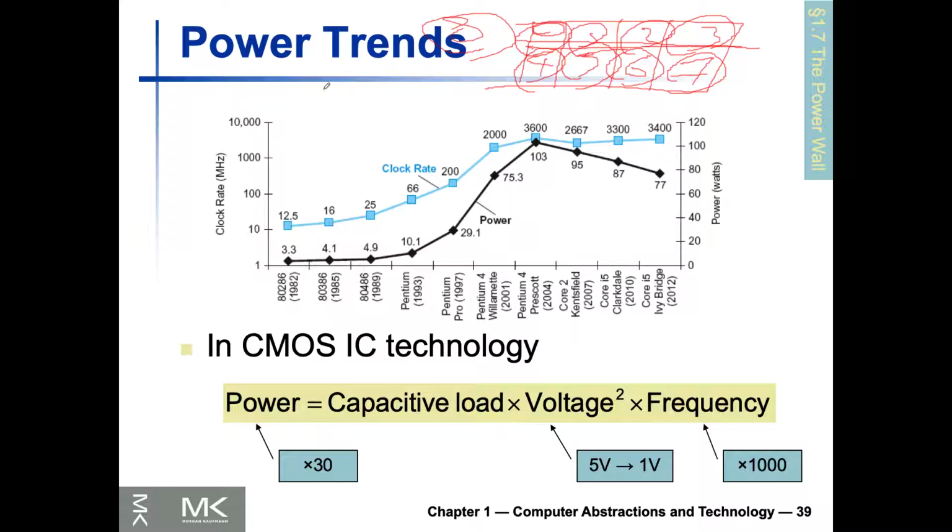You can see that not all of your cores are on at the same time. Perhaps this one is off, this one on, and they try to avoid having adjacent cores on at the same time because of their impact on each other. This problem is known as dark silicon.